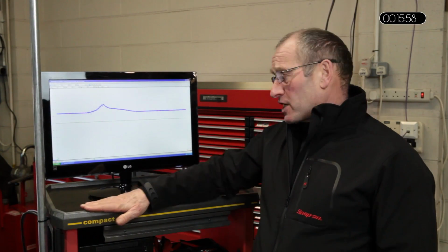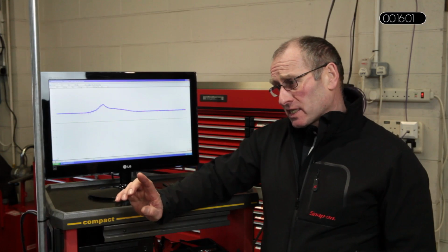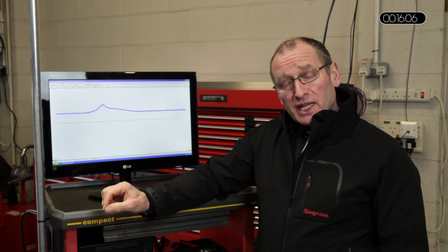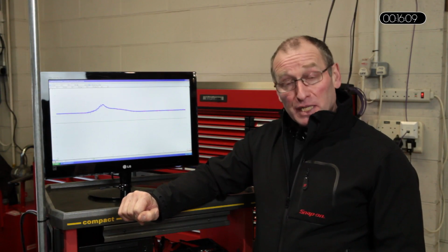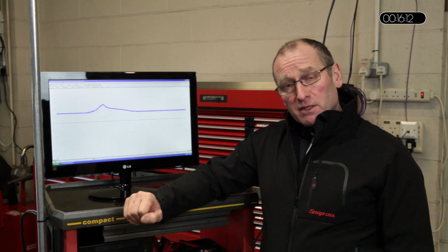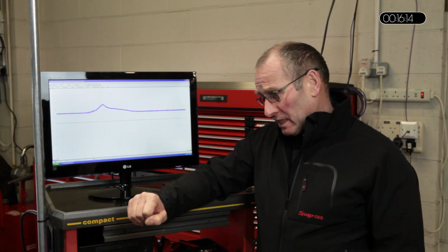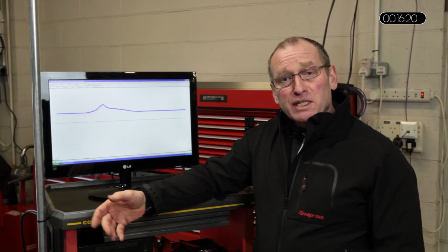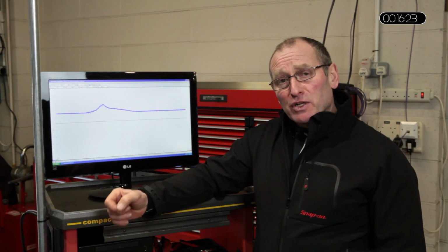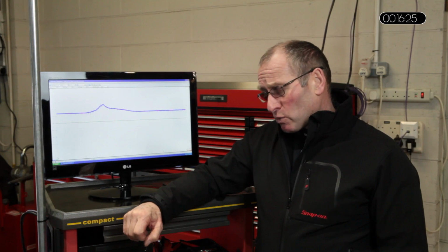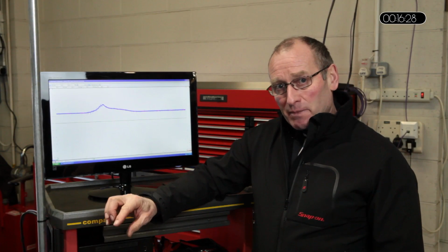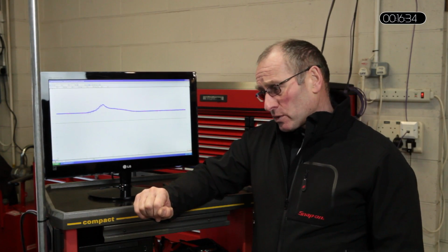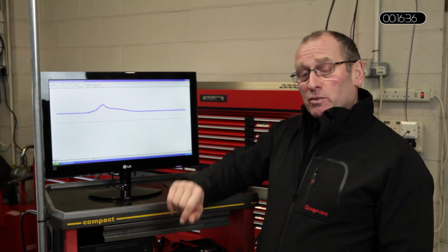Welcome back to the DPF presentation. So far we've looked at serial communication as an option for diagnosis. We've looked at using a digital multimeter as a very simplistic but very effective way of confirming that there's an excessive pressure generation in the vehicle. Simplistic because connection's easy, it's in real time, the numbers, the voltage is very easy to deal with. Remember, we're looking about 0.6, 0.7, key on static, with a maximum figure on the road dynamically of around 1.7 volts. Now, it's that figure I'd like to perhaps demonstrate pictorially with the use of the oscilloscope.